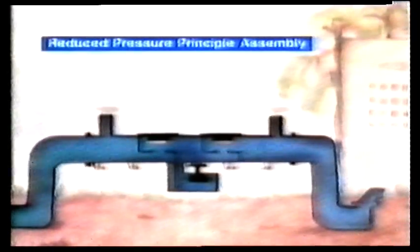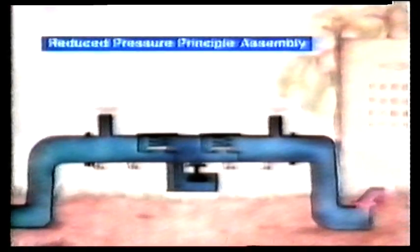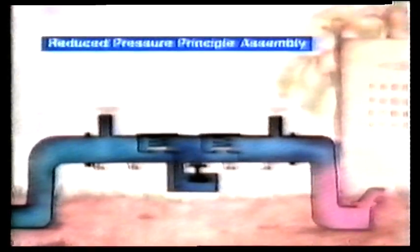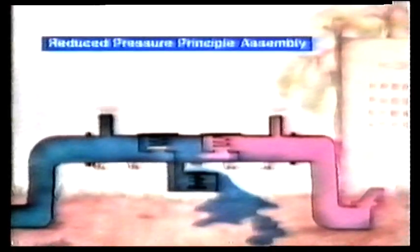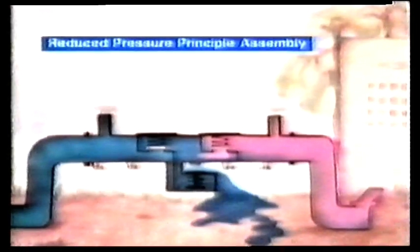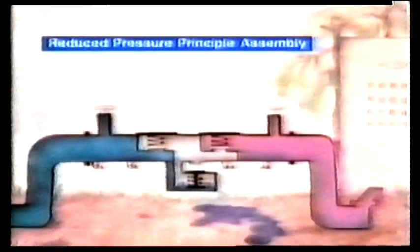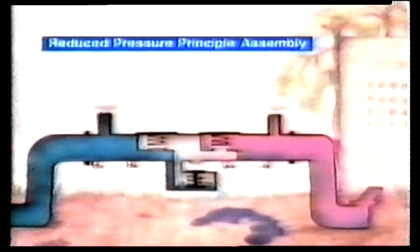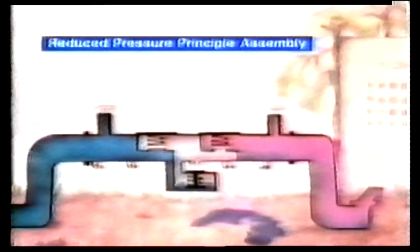But look what would happen if, for whatever reasons, the water is back-pressured through a leaking second check valve. Well, the differential pressure relief valve would open, creating an opening in the center chamber, draining the water completely out of the assembly, and thus never reaching the first check valve. Any substance that somehow made it past this check valve would now flow harmlessly through the opening and completely out of the assembly. This reduced pressure principal assembly is almost fail-safe. However, any mechanical device is subject to failure, so an extra measure of protection is necessary in certain applications.